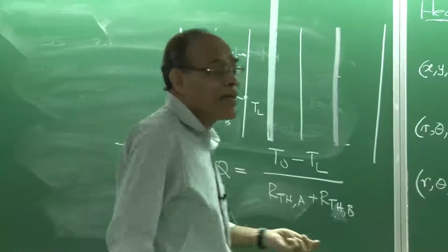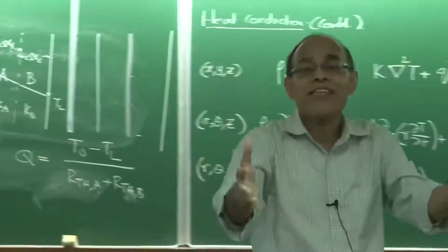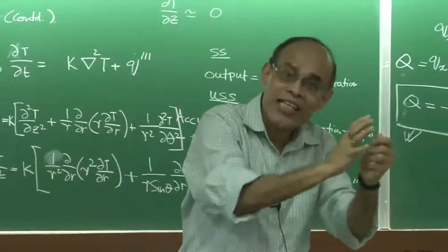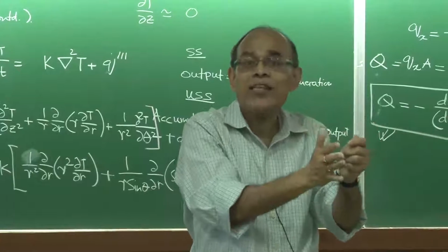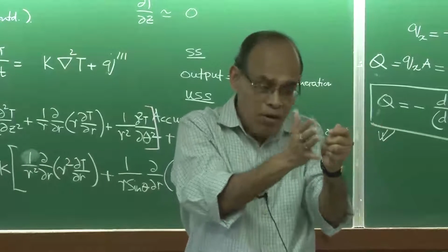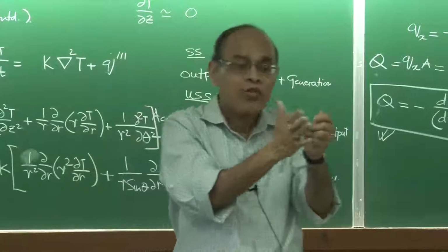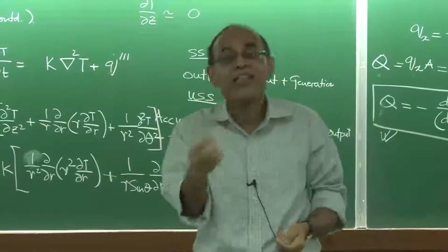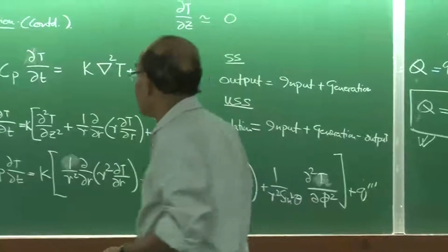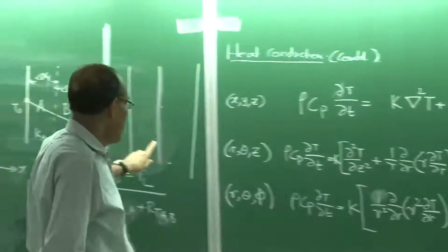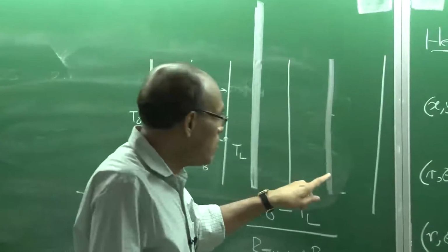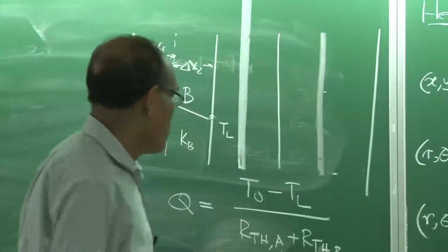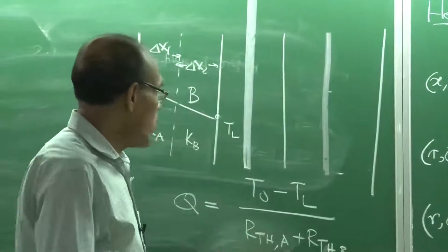For example, you can imagine that when you line a refractory vessel, the outer thing is the steel shell, but then you put the refractory on the steel shell, and there is a certain interface between the steel shell and the refractory. So, there is no perfect contact between them. There are always inhomogeneities at the contact, because it can have impurities, it can have air entrapped. So, we will discuss this interfacial contact resistance between the two surfaces when we talk about the applications towards the end of our lectures on heat conduction.